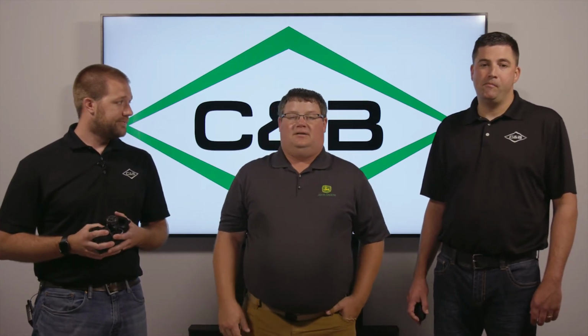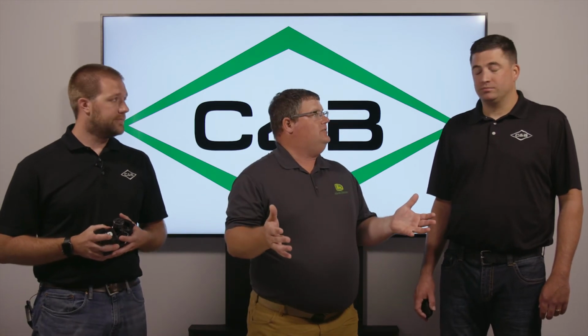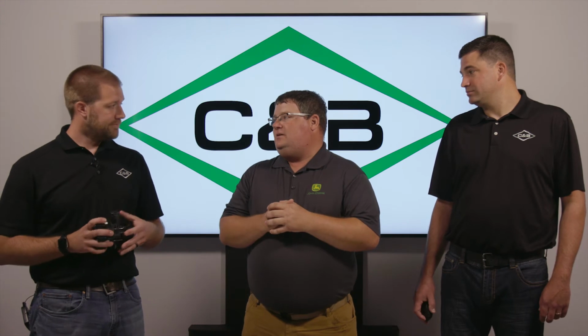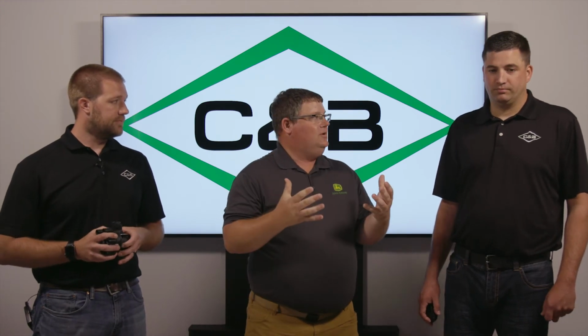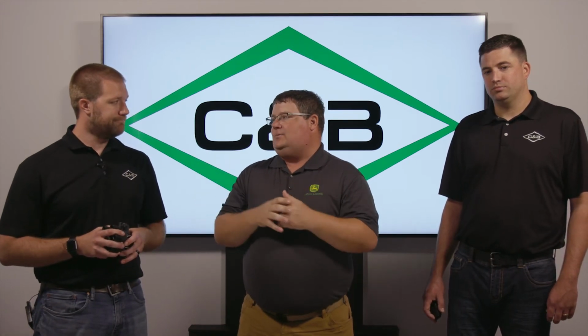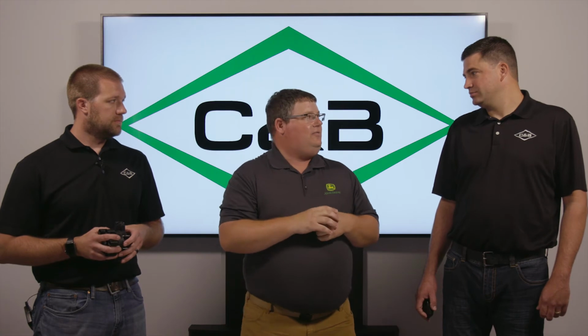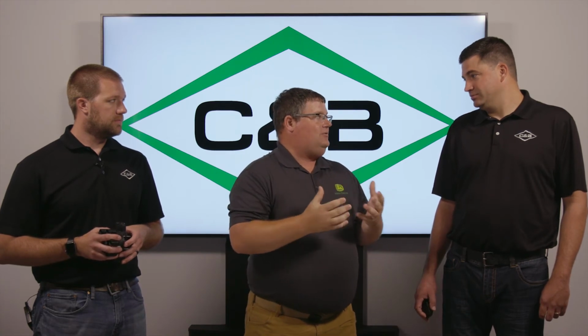Right. You bet. And that 10 hertz versus 30 hertz really comes into play. And if you get that boom low to the ground and you're traveling at high speeds, especially maybe some pre-emerge work, that's where we run into issues with maybe that 10 hertz. If we see what we call checkerboards in the fields of maybe some weeds that got some escapes, maybe we didn't get enough residual product down there to help control the weeds in those checkerboard areas, and you start to see that weed escape later on, where that 30 hertz is really going to help reduce that potential.